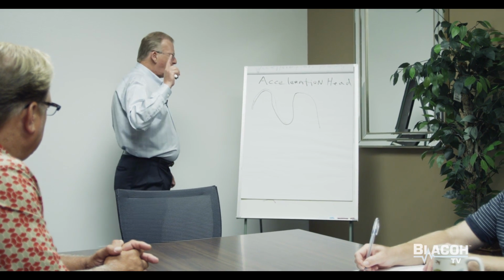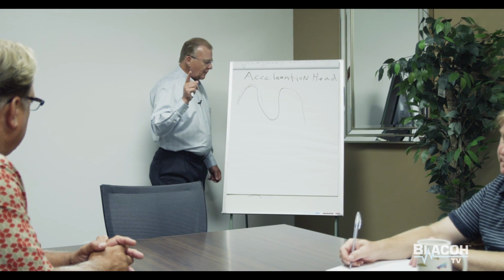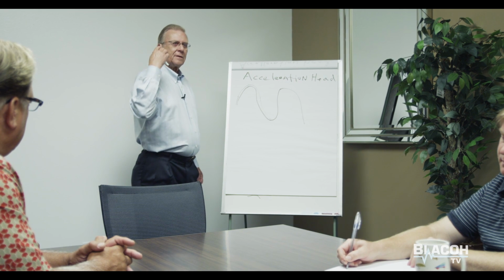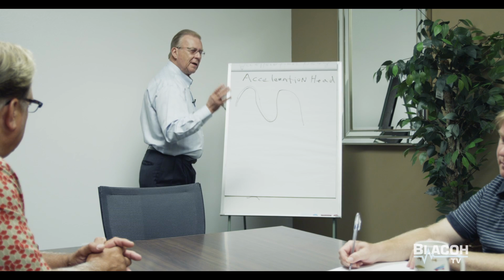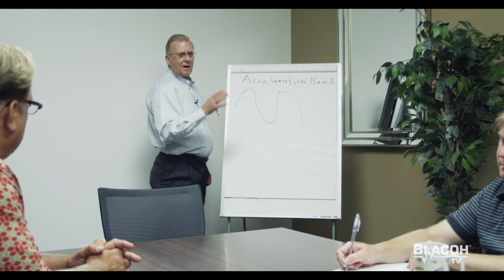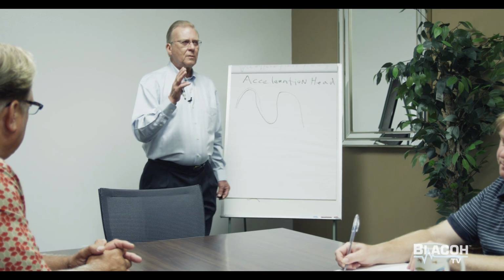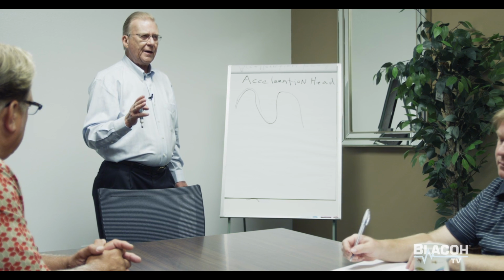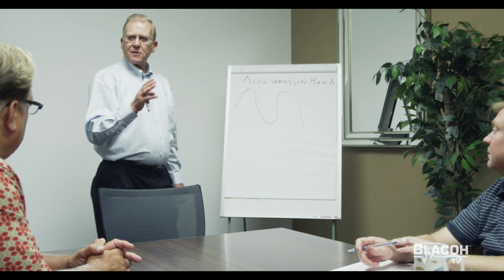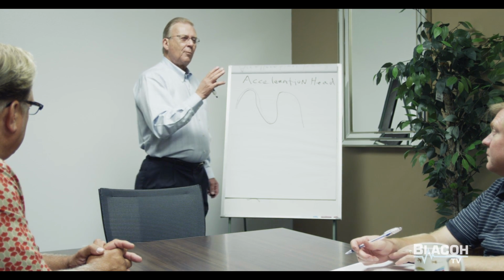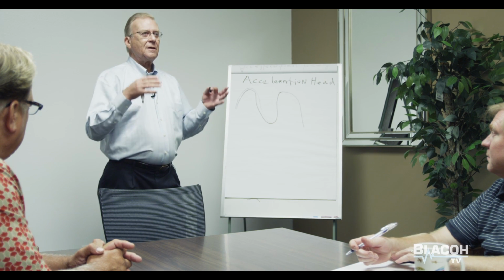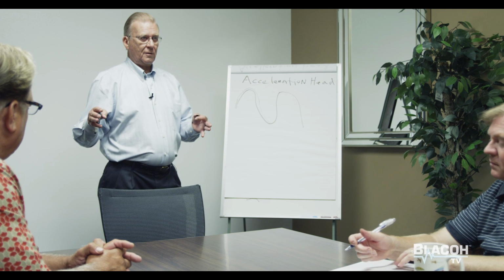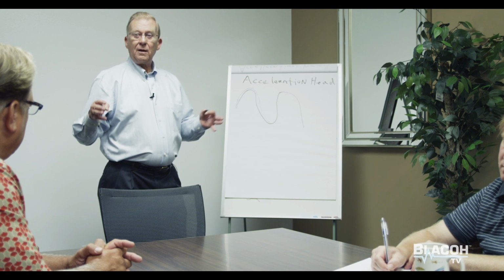Now the point of this is, and we're going to talk about the discharge side of the pump, but also the inlet side of the pump, but the point of this is, and as an aside, just remember when we're talking to people that all friction charts that are published, which is a pressure loss per typically 100 feet in a pipe, are based on steady state flow. Okay?